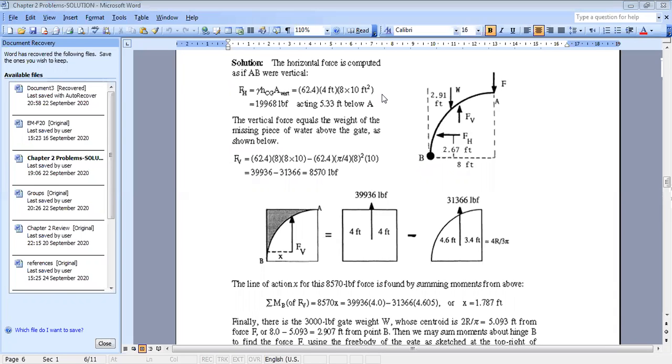if you have several forces and you want to reduce them to one force, you say that this force should be equivalent to all of them. So it should be equal to the summation of all forces acting on the system. And its point of application should be such that it produces the same moment about any point.